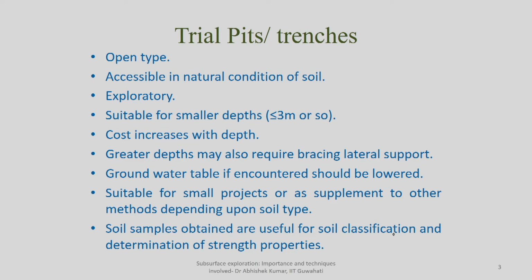Then if you encounter the groundwater table, you have to report it, and then you have to make arrangements by which you are able to lower the groundwater table temporarily, as long as your investigation is going on. Then it is particularly useful for smaller projects where the depth of foundation may be 1 meter, 2 meters, 3 meters below the ground surface. So, you can get an idea whether at that particular level where you are going to rest your foundation, you are actually getting sufficiently stable soil, sufficient stiffness of the soil, and then you can lay the foundation.